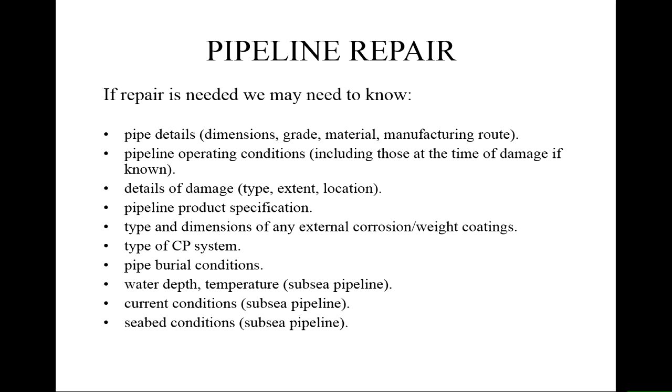In order to assess what caused the damage, and can we continue to operate the pipeline in the present conditions? Because if we cannot, if the damage will proceed at a high rate, then we probably need to choose one of the two options: replace a section of the pipe or downrate the pipe.